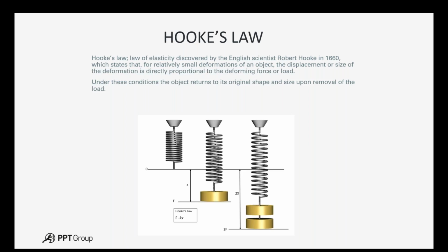And it's very important for material scientists to look at the elastic region of a property, because up to the end of that elastic region, removing any force on it will allow the material to return back to its original size. Once we pass this region, we enter the plastic region, where we start to have permanent deformation on the sample, which means the sample is getting slightly damaged. We continue past this, and then we obviously can break the sample.